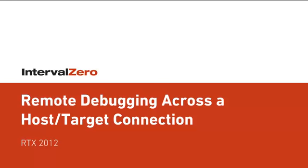Welcome to the Interval Zero video tutorial on remote debugging across a host-target connection. In this video, we will show how to configure a target 32-bit Windows machine to receive remote debug connections and set up a 32 or 64-bit host machine to communicate with the target for remote debugging of RTX applications in Visual Studio.